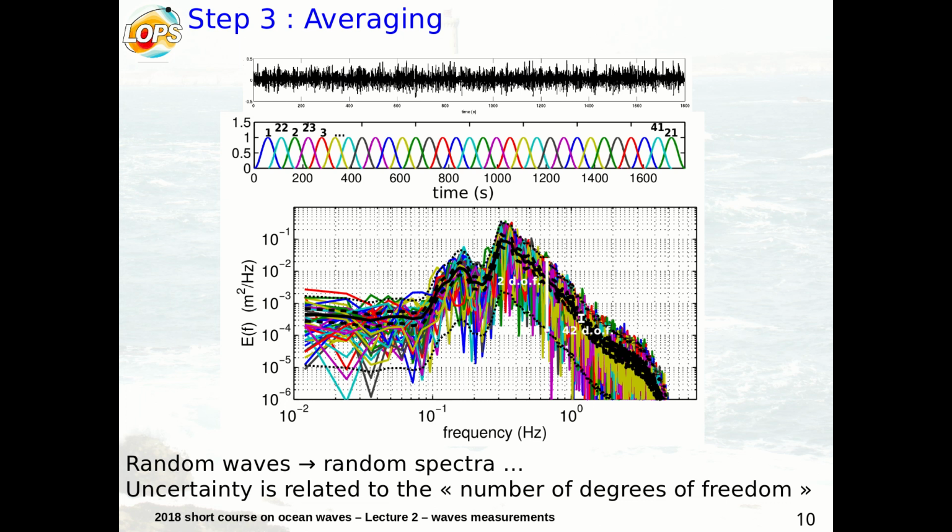And this is what you see, these dotted lines. Actually, there's one or two spectra that fall outside, and that's because I have 21 windows, but I also take windows which are shifted by half, and this is called the Welch method. When you take the window, you are losing information, so you take the window again and shift it.